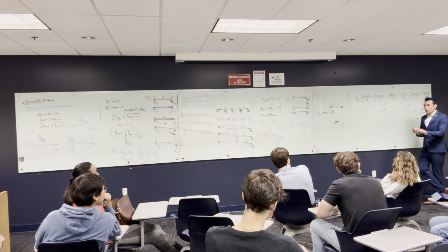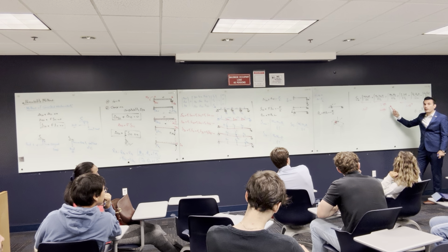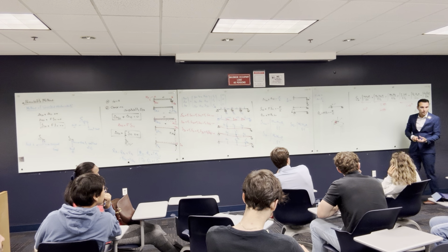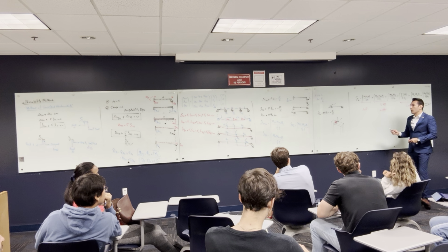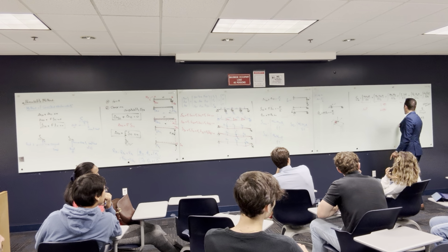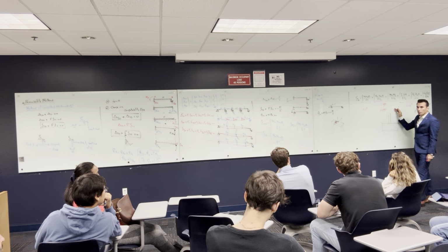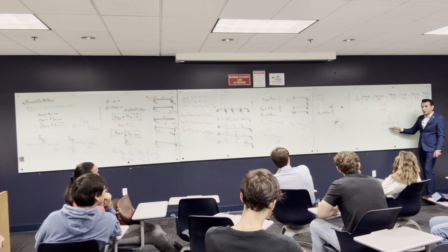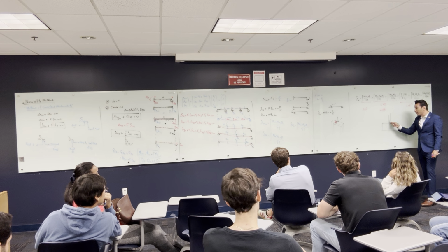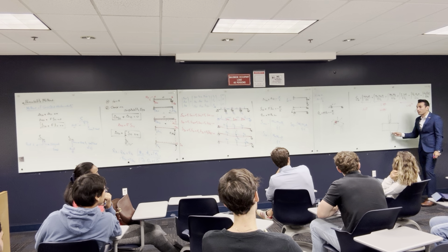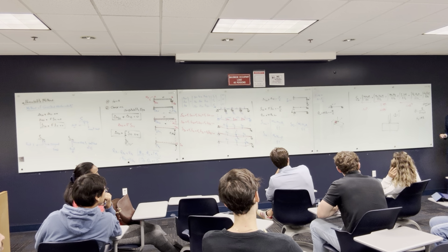So we usually rely on the moment deformation because it contributes to 95% of the total deformation, right? Always? Is there any case where it doesn't? If you have a high shear force, like I said before, if you have a really deep beam, and you have a column that holds 100 stories or something, and you have a transfer beam so that you can make this column not show up, and this is a really big load, you are going to have a high shear force, so your Q is really high, so it's going to make this value high, okay?